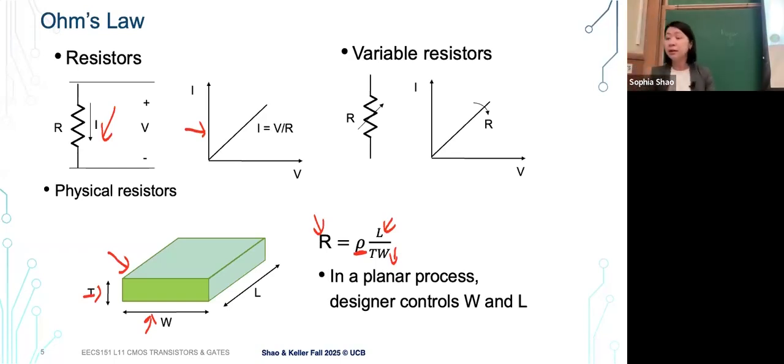So that's how we think about resistance of the particular device. It's related to the resistivity, a material property of the device on its own, but also related to the physical dimensions: how long it is. If it's longer, typically higher resistance, and how big the cross section is, both the width and also the depth. In most of our discussion today, we'll mostly focus on the width.